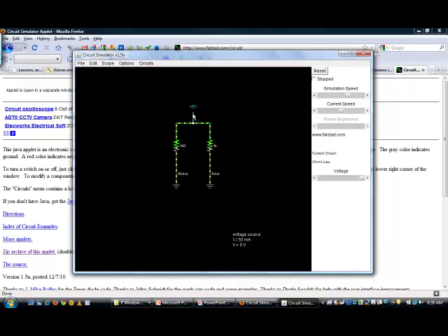V is 5 volts. Notice another thing about this simulation. We have different colors. Everything is green here, and then it's grayish here, and the color changes from green to grayish through the resistors. Actually, the color represents the voltage value. Wires with the same color are at the same voltage. That's quite an interesting, useful pedagogical tool. So now here we have only perfect wires on top of the resistors, so we should have the same voltage.